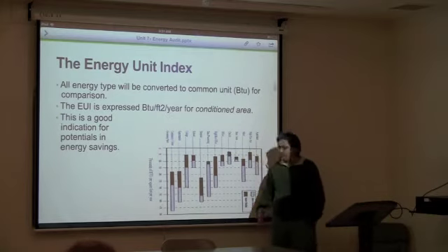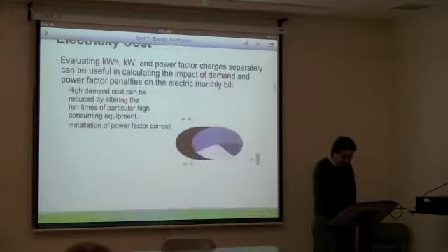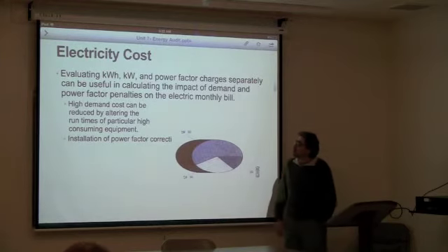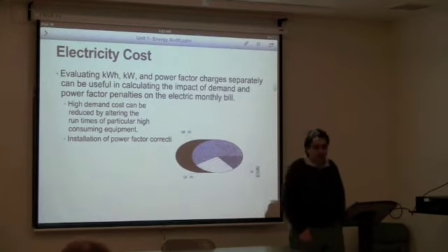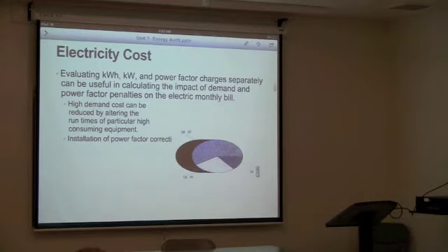And if it's about electricity, converting it to BTU might not be a good idea. It's better to keep it in kilowatt and kilowatt hour, right? Kilowatt is the power, the energy per second. And kilowatt hour is when you multiply that by the total hours to give you the energy. So kilowatt hour is energy, kilowatt is power. And I need both of them. I don't just need energy.